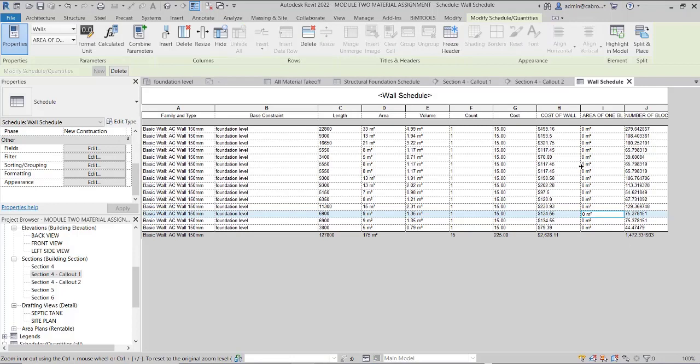So this is clearly evident that you can use Revit to do all your quantity calculation. If you even want to bring in formulas from estimation to calculate, you can even calculate the number of bags of cement that you need for your concrete, for your block work and everything. You can just do it on a table, and then it pulls it up straight away for you. So it's easy to go around with this. Let's continue to try our hands on as many areas as we can, and I tell you, we'll be glad we picked up this program.